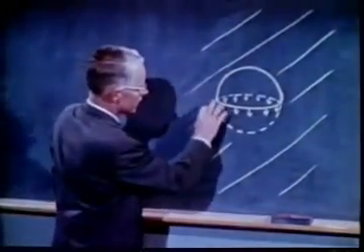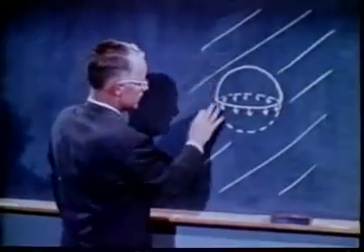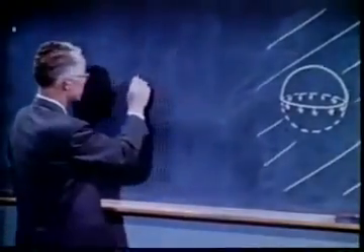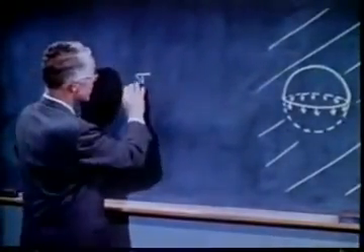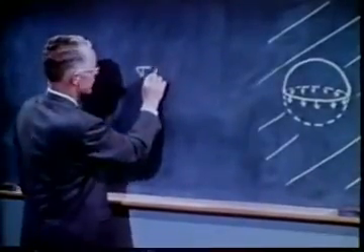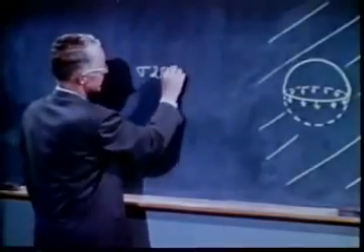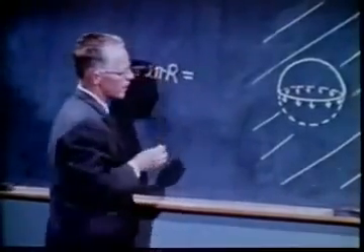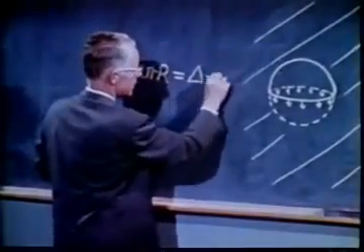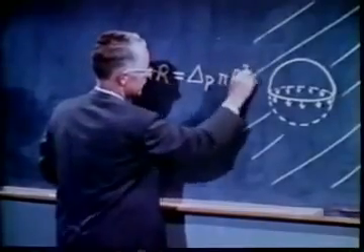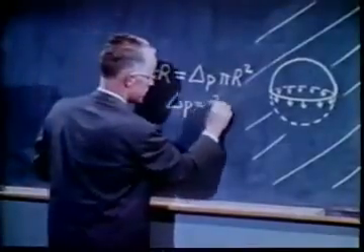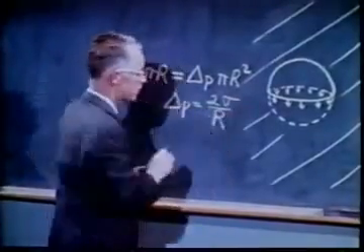Consider the upper half of a gas bubble immersed in a liquid. Surface tension will pull down all around the equator with a total force equaling the surface tension expressed as force per unit length times the length of the circumference. That must be balanced by an upward force, the pressure difference, times the area at the equator. This simplifies to the pressure difference equaling twice the surface tension divided by the radius of the bubble.